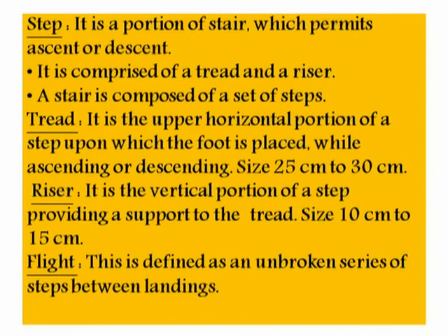The size is 25 to 30 centimeter. Riser. It is the vertical portion of a step providing support to the tread. That vertical part is known as a riser. The size is 10 to 15 centimeter.